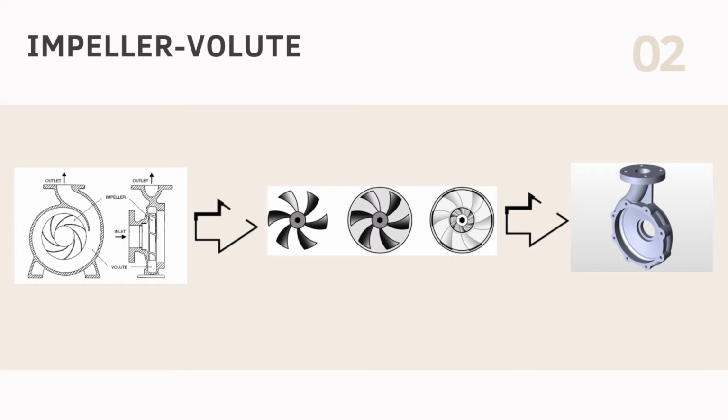The impeller's blades are responsible for the rotatory movement of the pump, and their number varies according to the design. The volute is a piece that has the function of converting the kinetic energy of the fluid into static pressure. Besides these two components, the impeller width, blade dimension, attack angles, and other characteristics are important in the process of designing a centrifugal pump. Different methods exist that help in the construction of effective pumps at a specific condition, that not only satisfy the necessities and requirements of the client, but also avoid common problems like cavitation.